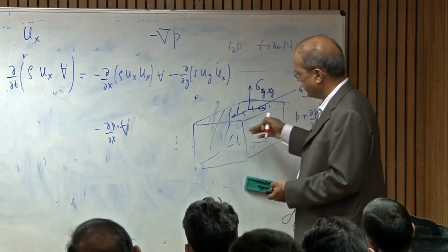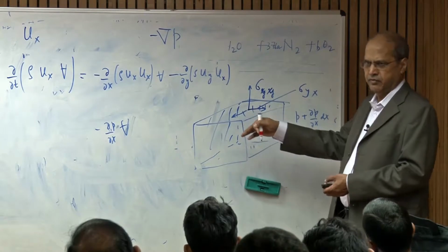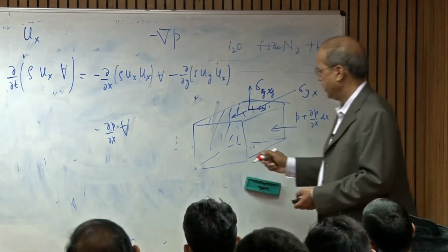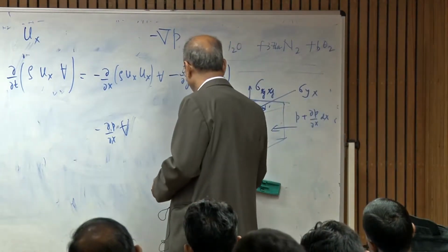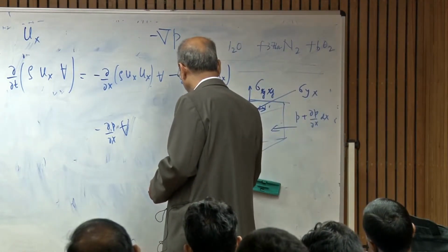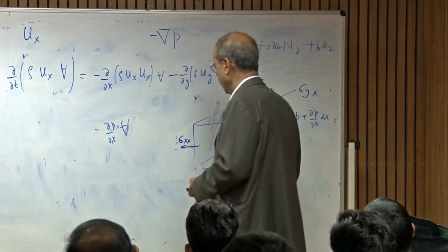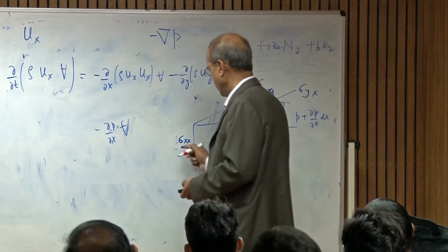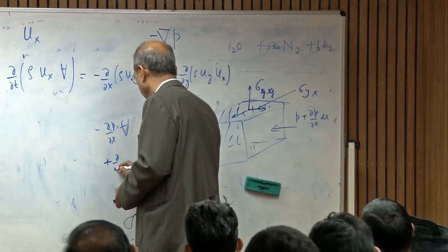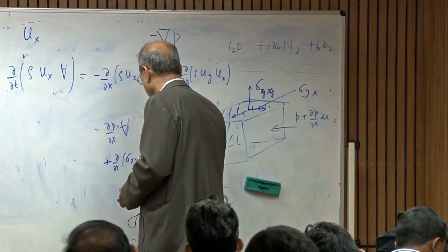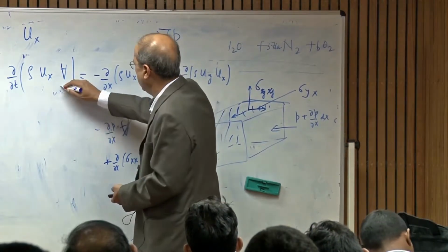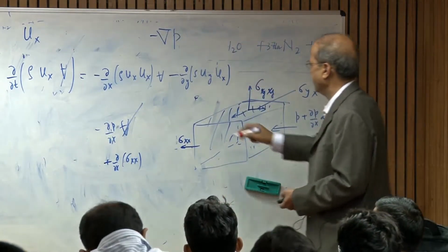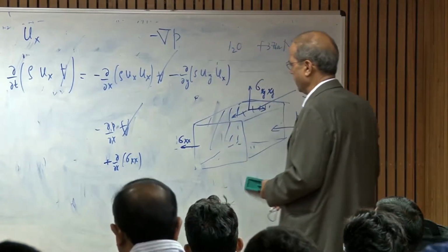Look at what are the forces due to viscous stresses which are acting in the x direction. First of all you have sigma xx, and the direction is opposite of the pressure force. So this will give us d dx of sigma xx. I'll just skip writing volume all the time because there's no need to write volume everywhere, since we divide by the volume.